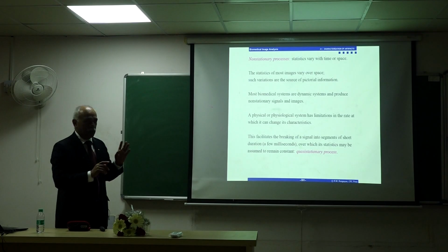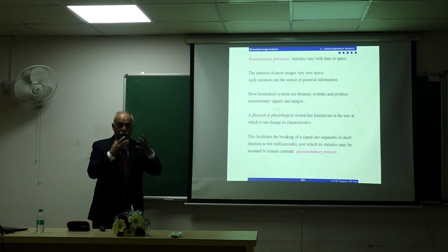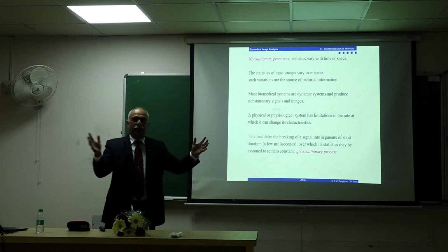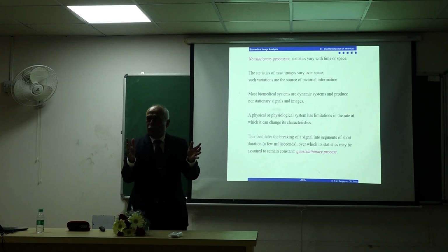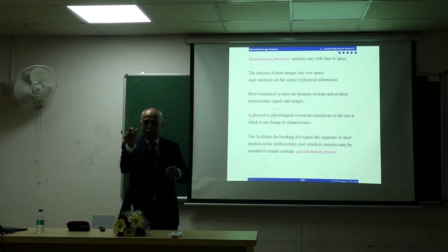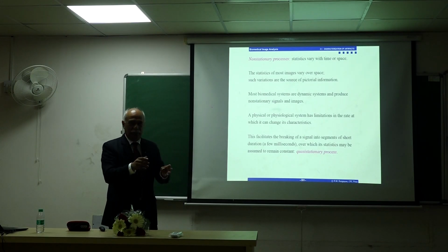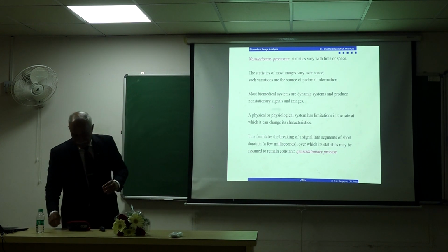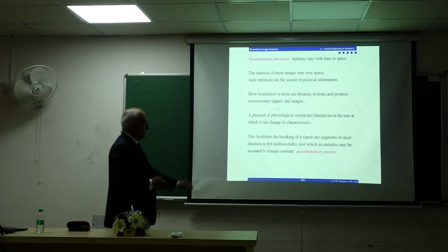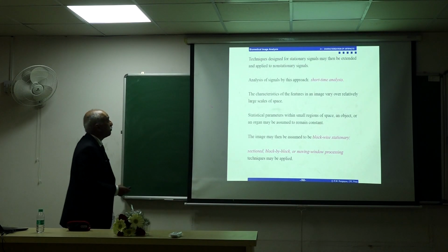This is commonly done in speech signal processing using what is called short-time signal processing. You don't take an entire speech of several minutes and analyze it in one shot. That's not possible. You take short pieces, short-time analysis. Within those short windows, you assume the signal has the same spectrum, same autocorrelation. It is stationary. So that is then the notion of quasi-stationary processes.